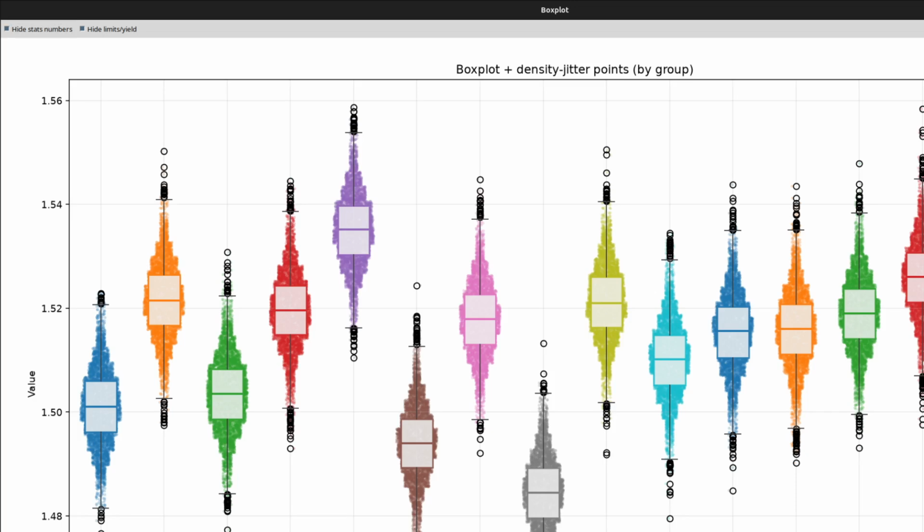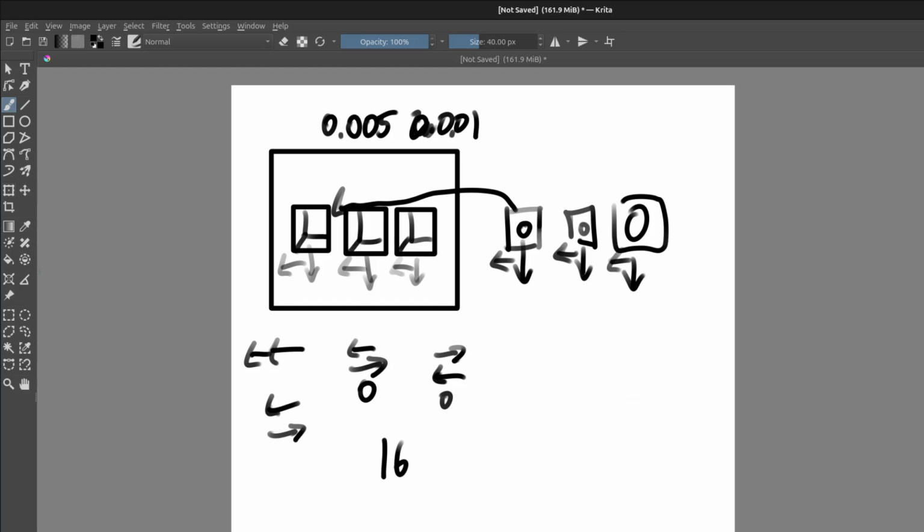And if you do that over a couple of different positions for each insert, you can find out what the actual true deviation is of the insert versus the pocket to a finer accuracy than what you would be able to do just by doing extremely high accuracy measurement. Because this is actually looking at the actual end good, the functional part that's coming off of the process.